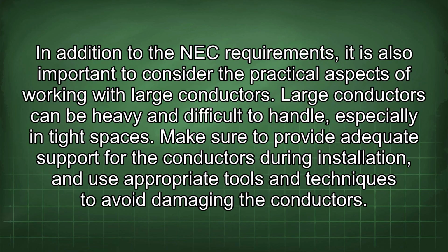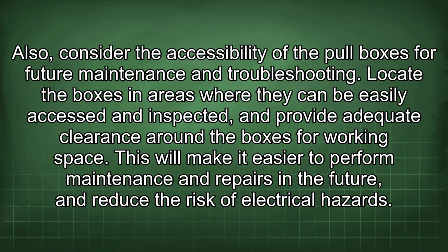In addition to the NEC requirements, it is also important to consider the practical aspects of working with large conductors. Large conductors can be heavy and difficult to handle, especially in tight spaces. Make sure to provide adequate support for the conductors during installation and use appropriate tools and techniques to avoid damaging the conductors. Also, consider the accessibility of the pull boxes for future maintenance and troubleshooting.